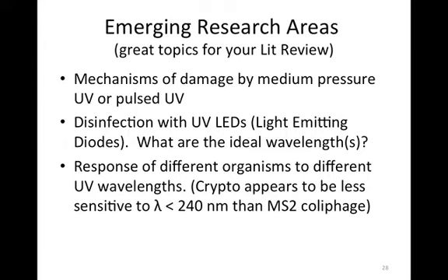And then finally, there's some work going on showing that different organisms appear to respond differently to different wavelengths. So that summary table that shows the sensitivity of organisms at 254 nanometers, the order of those organisms may change at other wavelengths or with combinations of different wavelengths. So that's kind of interesting.